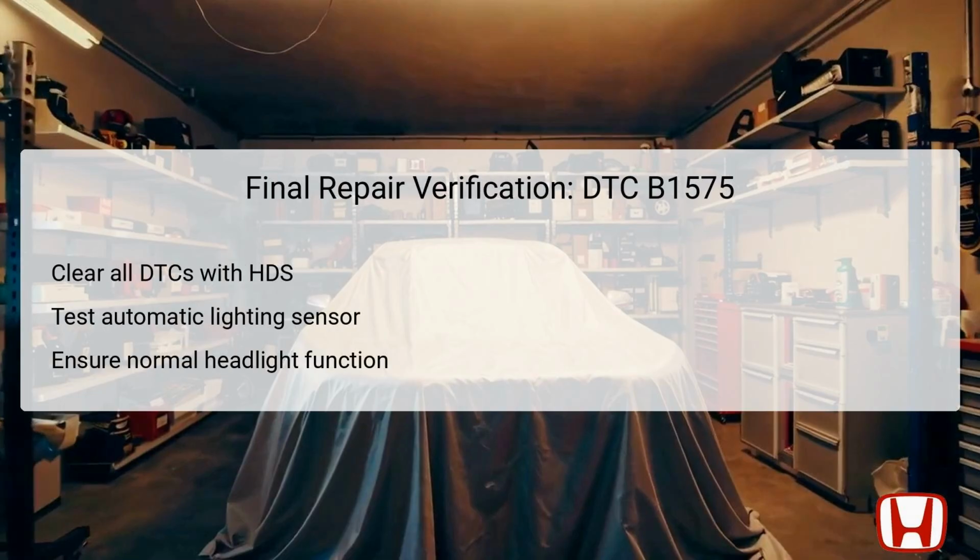Once repairs are conducted, it is vital to perform a final verification to confirm the successful resolution of DTC B1575. Start by clearing all DTCs with the Honda Diagnostic System, HDS, to reset the vehicle systems. Then, test the functionality of the automatic lighting sensor to ensure that it operates correctly. Observations should be made regarding how the headlights react to varying light conditions to confirm proper adjustments.